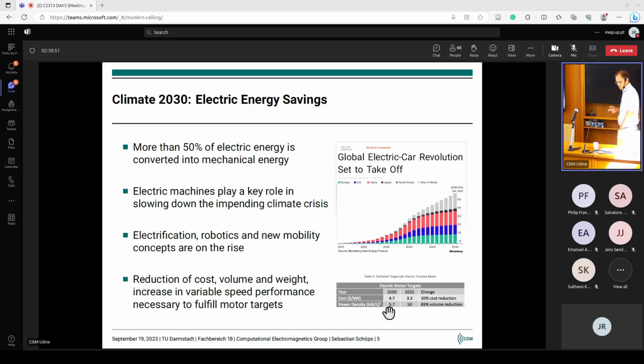And since many of you are engineers, it's not just that you make things smaller. I mean, you have less volume to remove the heat. That's the actual problem. So I would say one of the biggest problems now in designing electrical machines is not so much the magnetics, which is well covered since 200 years. It's how to get rid of the heat. That's the interesting part: how to get the cooling done. I don't know if you have these kind of people in your head who tell you, multiphysics, right? That's the person now screaming in your head, maybe. So you really have to do multiphysics simulation to reach such goals, which, and I will come to that later, is right now not the case in industry.